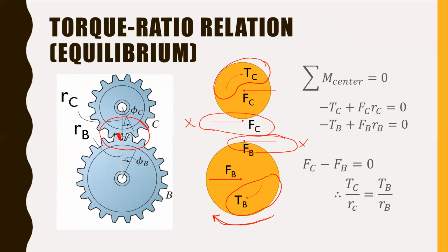Some people have difficulty reconciling that because they feel like gears should move in opposite directions. That's exactly the point. Gears do move in opposite directions. They rotate in opposite directions. But if you're going to stop that motion, you need a reaction that is the same. So I always bring things back to axially loaded members, because being from structural engineering, I think better with axially loaded members than I do with twisting members. So if I have, say, this member here, and I apply some force to it, this end wants to move to the right. This left end also wants to move to the right.